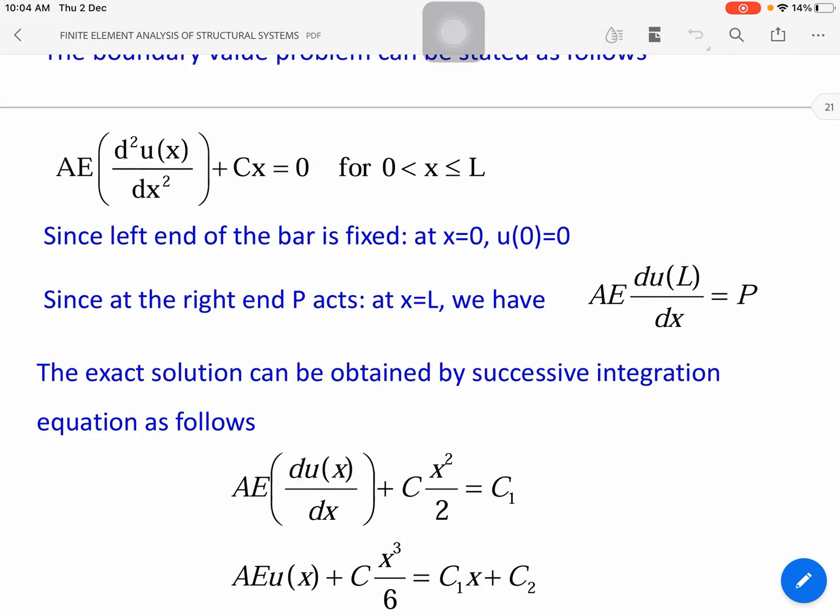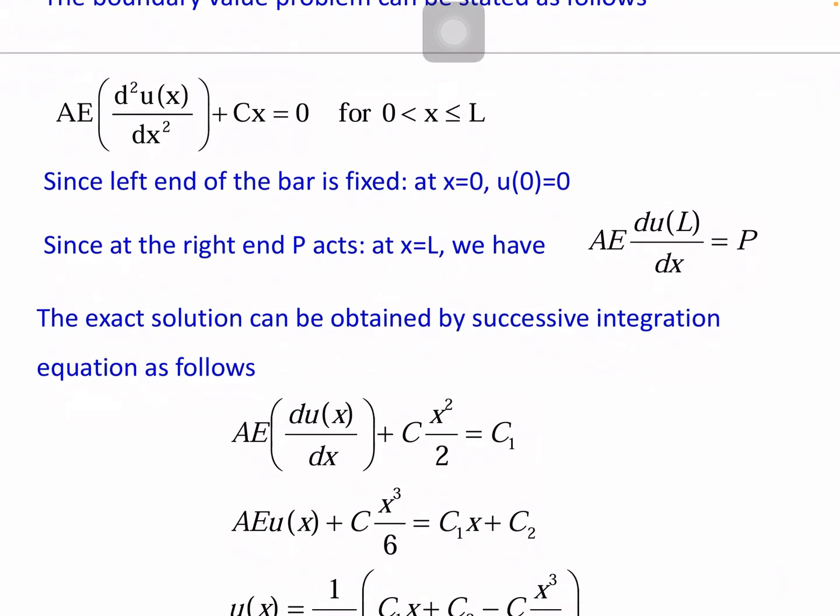So this is derived from the equation for axial deformation, which is equal to PL by AE. So u is equal to PL by AE. Since we have considered only elemental length dx, L equals dx, we can write here. From the PL by AE, this expression is derived. So here delta is equal to PL by E. From the equation delta is equal to PL by AE, from delta is equal to PL by E, this du is delta, dx is L. That is the difference.